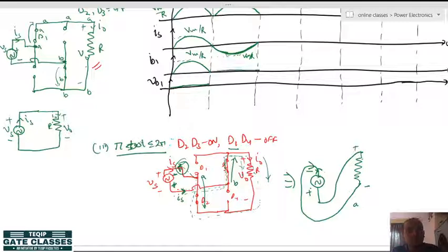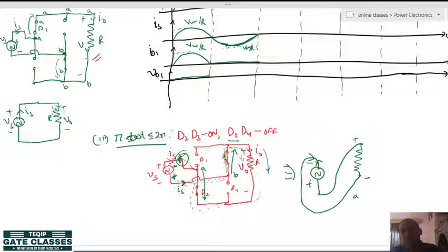Okay. And what is diode 1 voltage? Here diode 1 is also off. So, if you want to calculate the diode voltages, again we have to write the KVL equations. If you write the KVL equations here, the plus reference and the minus reference, you go from here: Vs minus Vd1, and from Vd1 we go with the V naught and then minus this Vd4.